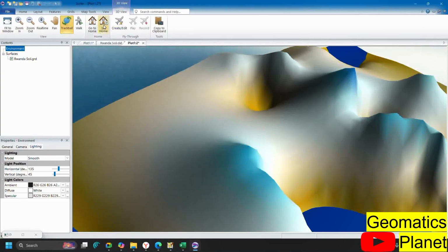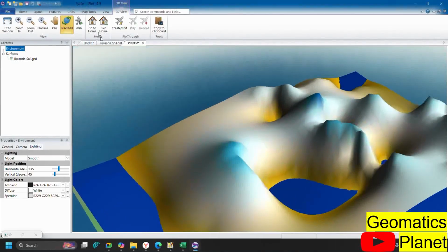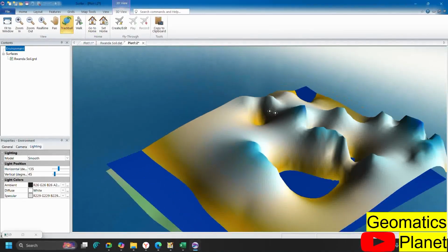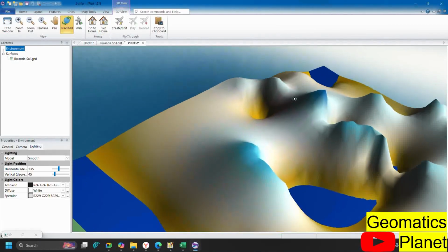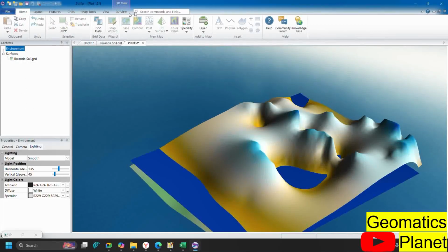You can create, you can edit, you can set this place as home. It will always know that this is your home. Anytime you click on go home, it will return here. So just like the way we do bookmark, if I put it here and say set here as home, anytime, even if I'm like this and I want to return home, I'll just click on go home and it takes me to that level. So this is the aspect of 3D view, which you can always return back, exit from 3D view, and this is under environmental.